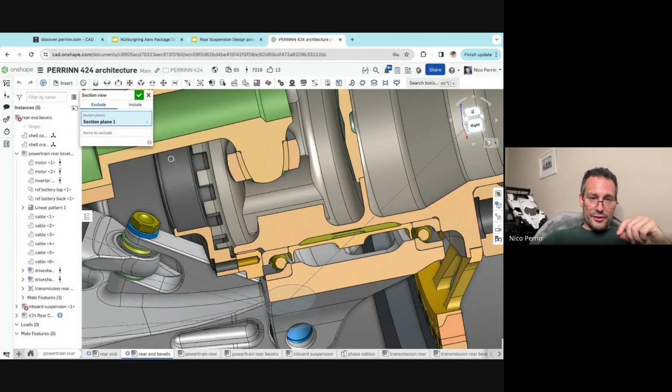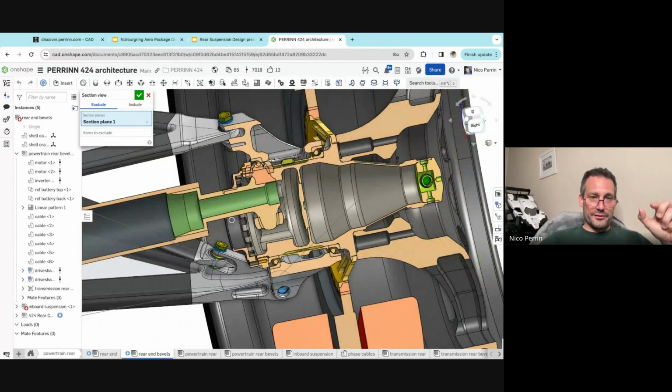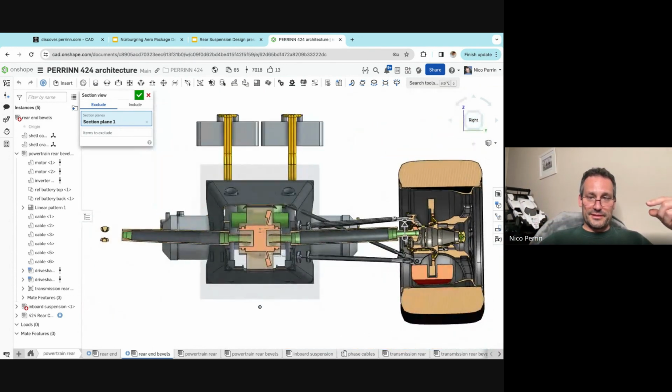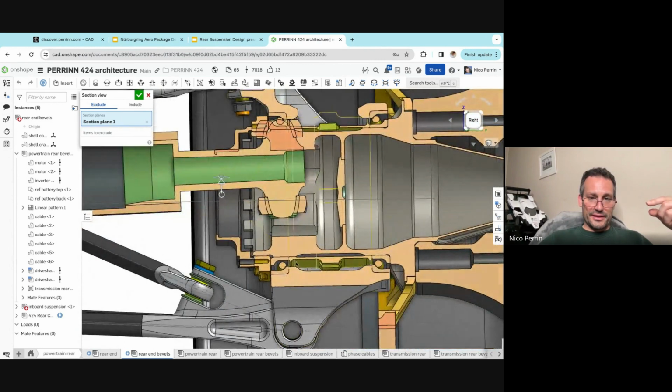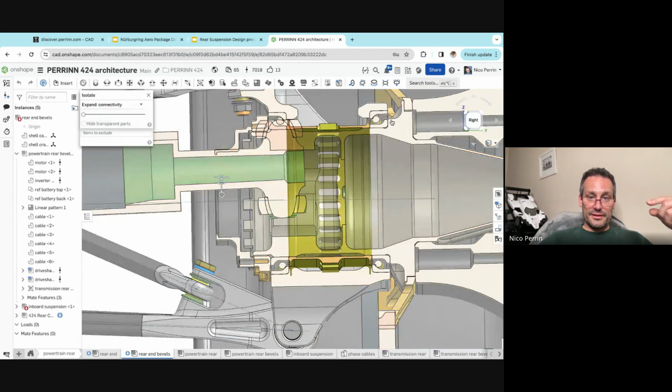So these are angular contact bearings. So you've got 1 and 2, and they're typically called high diameter, low profile. So they're very thin. They're small, but they're high diameter, and they're angular contact with a preload. And the preload is basically set using a spacer here, the yellow spacer, which I'm going to highlight.